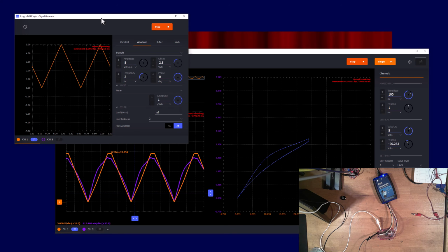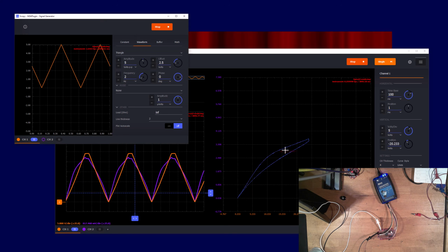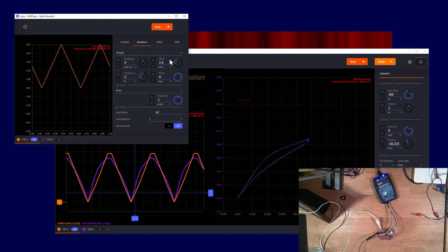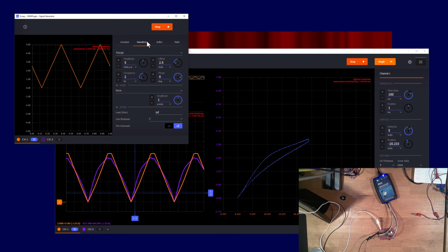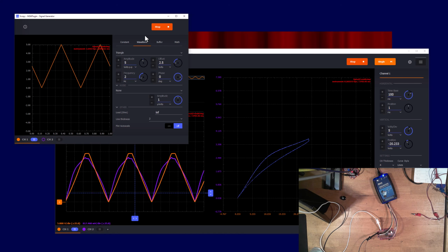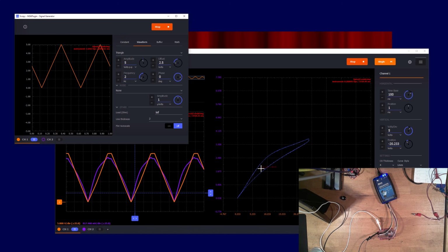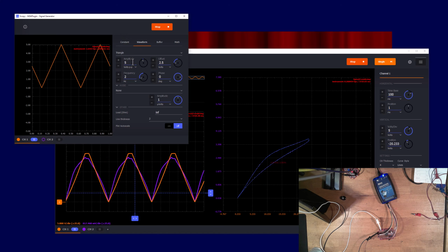So let's drop the amplitude and let's see if we can explore the different operating points along this curve here. So remember, the light bulb doesn't care whether it's AC or DC. The power is power. So whatever the RMS voltage across the light bulb is, whether it's the sine wave output from your signal generator or this trace, it's the RMS voltage that determines the power dissipation.